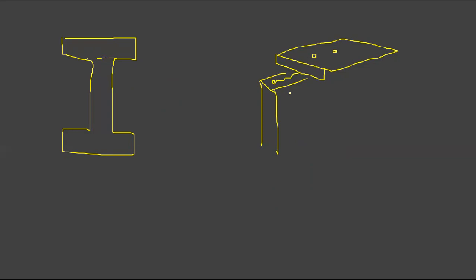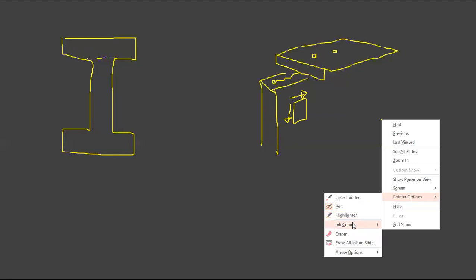If the nail fails, the problem is due to the shear, right? You know the shear is complementary, right? So if you take a small element, if you have shear like this, it will have shear in the horizontal as well. So we're probably talking about this complementary shear stress, right?